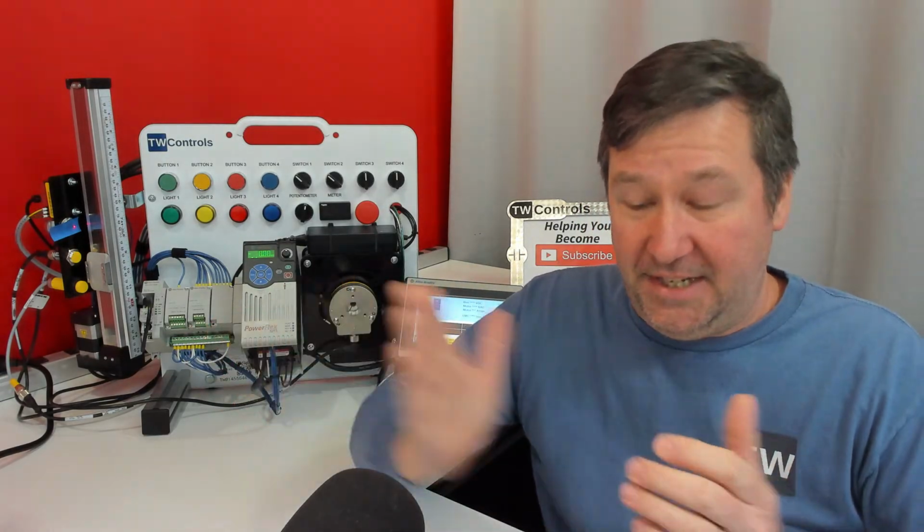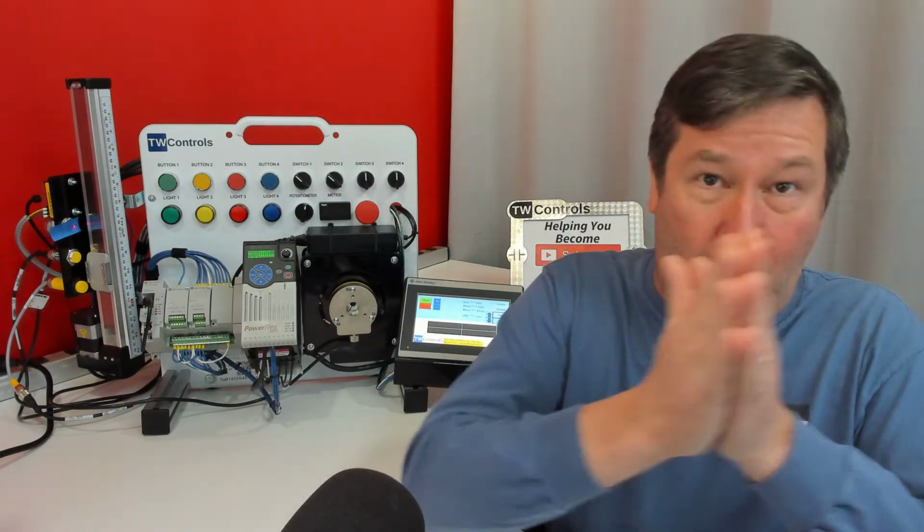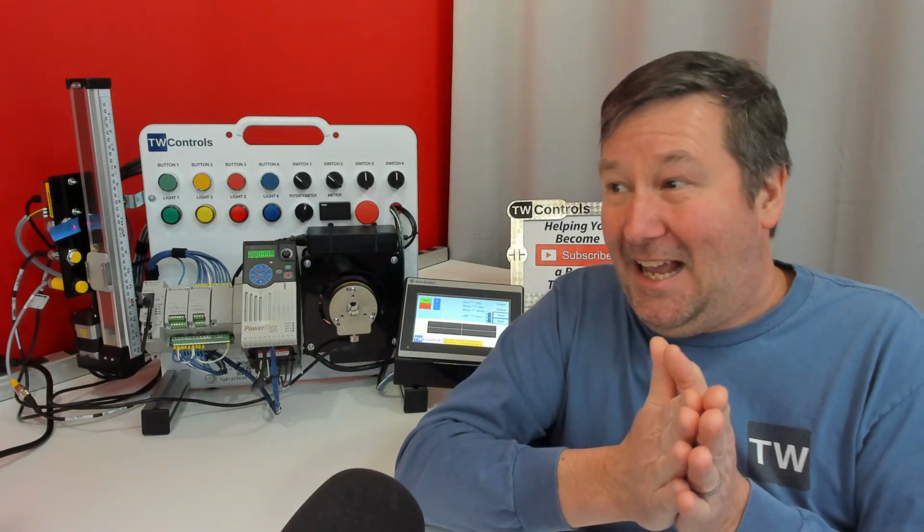An integer is a whole number. So our drive speed is 0 to 100%. That means we have 50 or 49 or 51. We don't have any decimals in between those. And here's where usually somebody starts typing right away. Well, my process is not that critical. It shouldn't matter. Well, yeah, you'd be surprised at the times that it does matter.